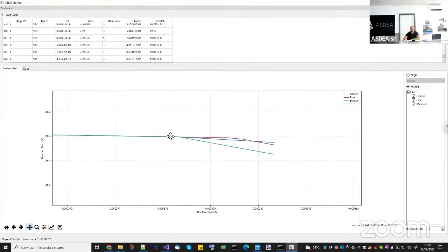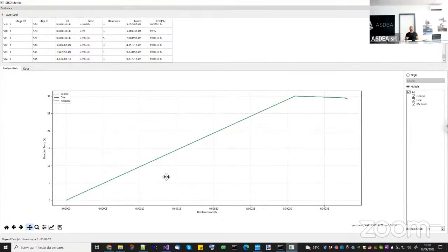Up to here. Then here something is happening. Basically, during the Newton iterations, the iterative scheme is introducing some error somewhere. So some elements will start to unload and the others will start loading. And this is what happened. Up to here, OpenSees is trying to reduce the time step, but it cannot find convergence. It's very difficult. Why? This is called the problem of bifurcation.